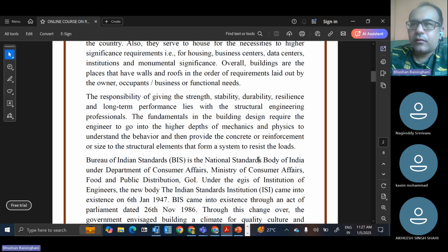it is a rigid connection by its very nature. If you are not providing reinforcement, it does not have tension capacity, so it will crack. Once it cracks, it will reduce the stiffness of that beam. However, your main beam is designed considering the secondary beam is there, so you are reducing the effective length of the main beam. So that will affect the design of the main beam.